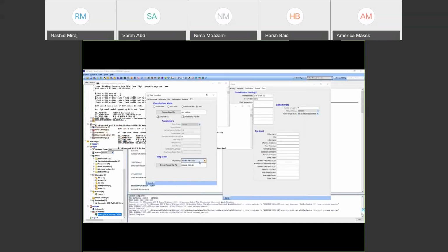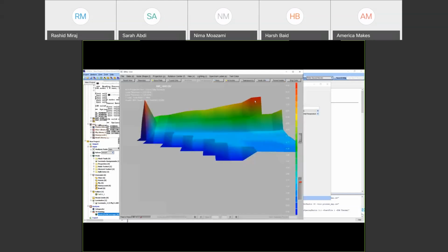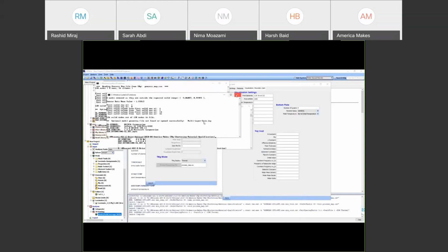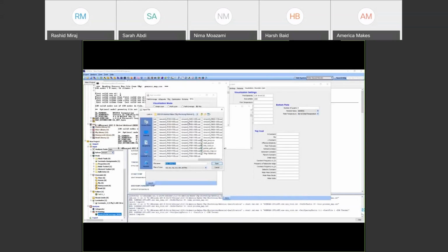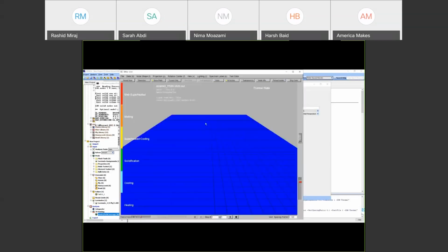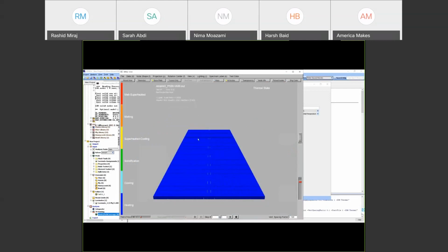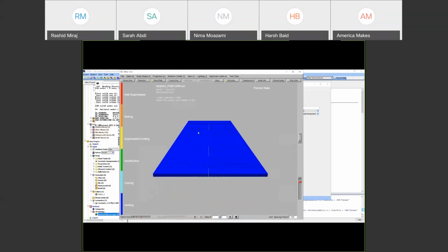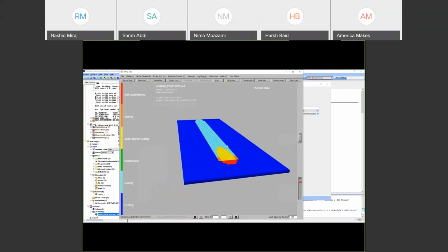But also, the question is, how can we come up with those two maps? We require other parameters, and we have to change the input file for the visualization, which is actually one of these binary files for different power speeds. So I'm going to show you other capabilities that are required in order to come up with the process map, which is melt pool, the thermal state.